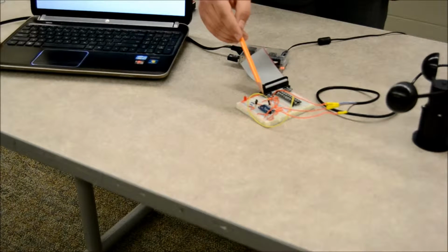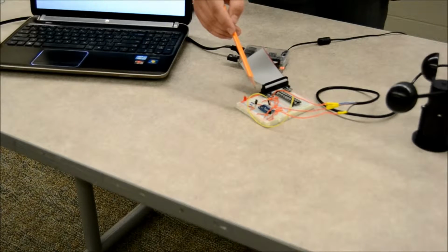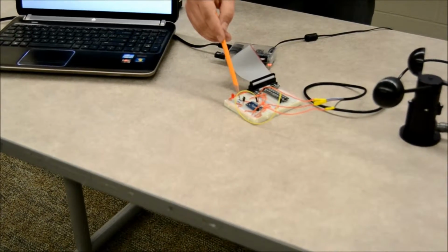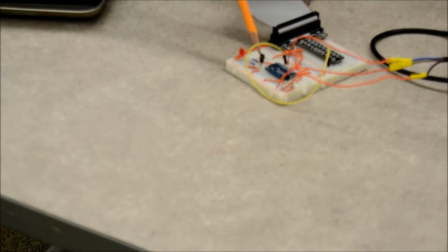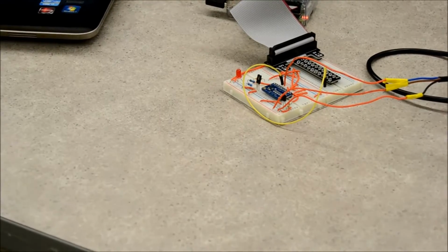The output of the humidity sensor is connected to a voltage divider circuit. The voltage divider circuit consists of two 100k ohm resistors connected in series between the output and the ground pins of the humidity sensor. The voltage divider circuit provides a safe range of the voltage that cannot exceed 3.3 volts DC for the ADC input to be used on the Raspberry Pi, which runs on 3.3 volts DC.